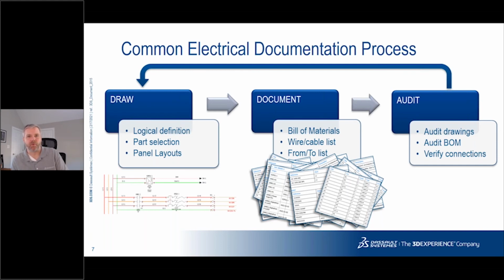When he had to draw wires, he didn't create a new layer so it would make a new color line for him. He grabbed a wire style for multi-phase power, and he was able to draw, and bend and fold and invert those lines very easily. What I also noticed is when he had to put a symbol on, the lines trimmed themselves automatically.